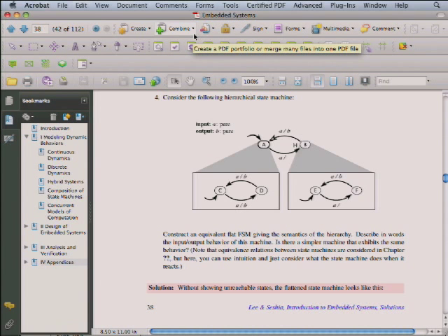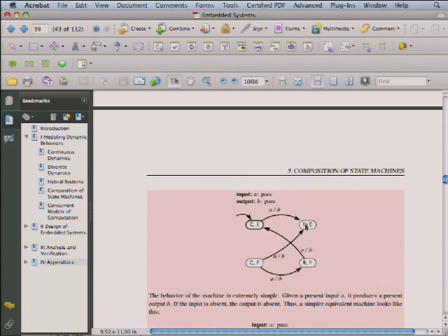So this is the one that gives the equivalent semantics for a hierarchical state machine, where you've got these two states, A and B, and it's got this reset transition from B to A and a history transition from A to B. And the equivalent state machine that's shown in the solutions is like this, but this arrow should go from B to E to C to F rather than from C to F to B to E. Otherwise, you would get stuck in this state.